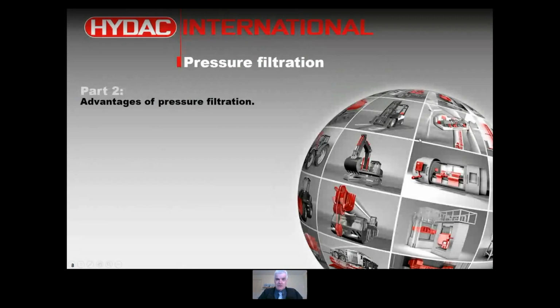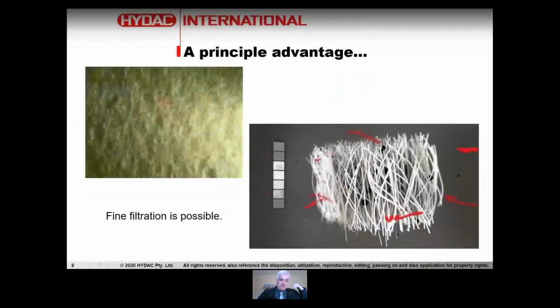Advantages of using pressure filtration. There's a very clear principal advantage, and that is because unlike suction filtration, where you have the risk of cavitating the pump, when you have pressure filtration, you can go fine. Fine filtration means ultimately that you're going to be able to achieve good cleanliness levels without damaging anything. You can do the fine filtration with the fine media, and you have pressure available to push that oil through the media. For those reasons, it works very well.